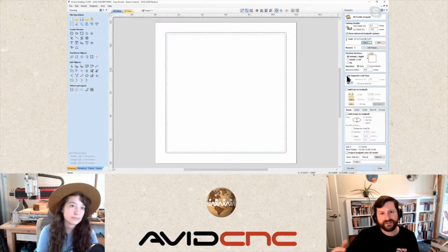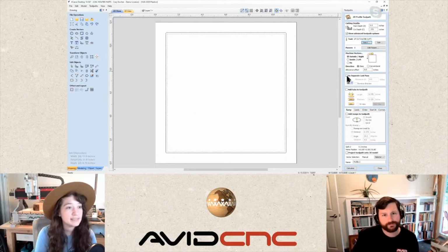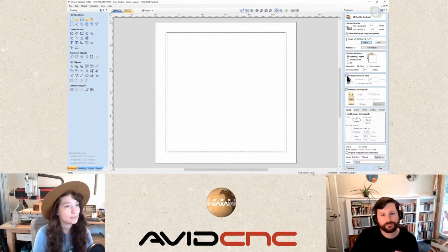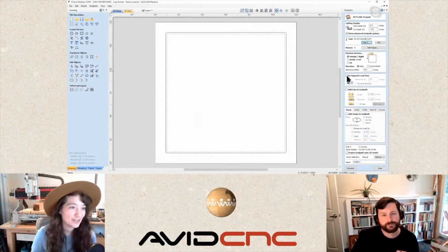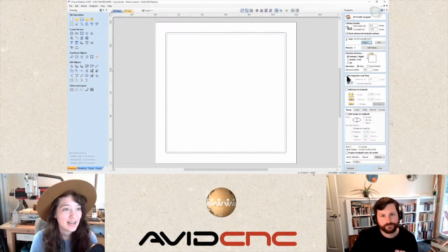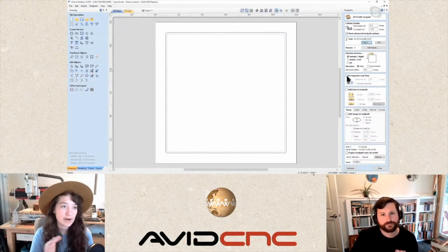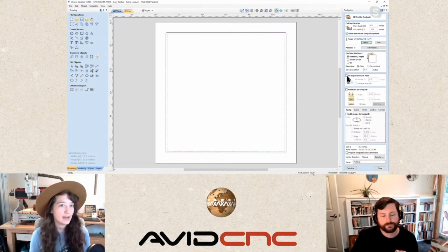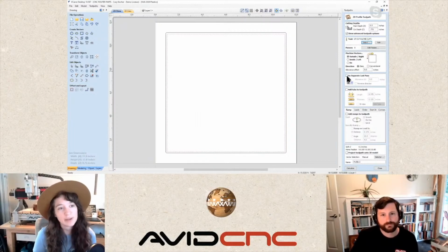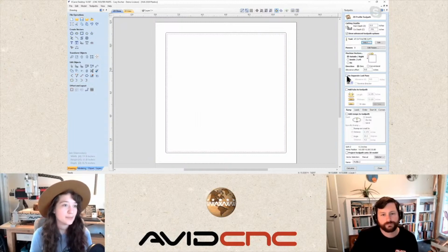Now, Sami, in this instance, would you use a last pass with acrylic when you were cutting all the way through? I think in this case I would, because I prefer not to have to do too much sanding, finishing to acrylic in particular, especially if there's a gloss surface that I don't want to accidentally nick with my orbital sander or something like that. And with the upcut here, you'll have a lot of room for chip evacuation. So I definitely think including the separate last pass in this circumstance is a bonus.